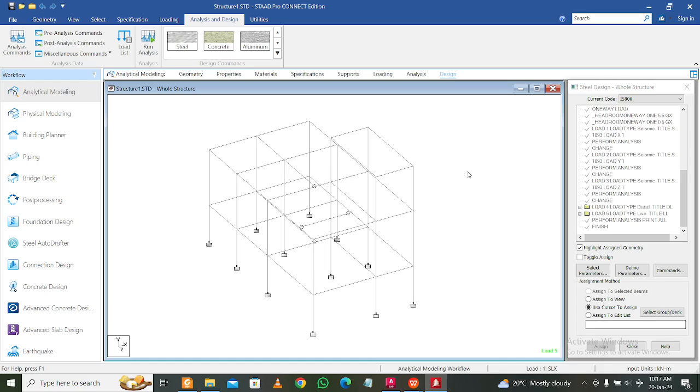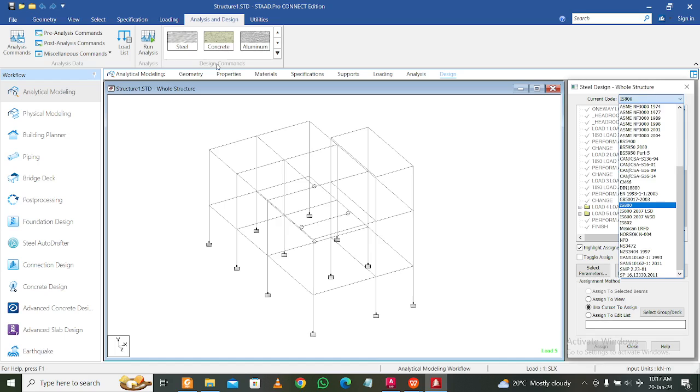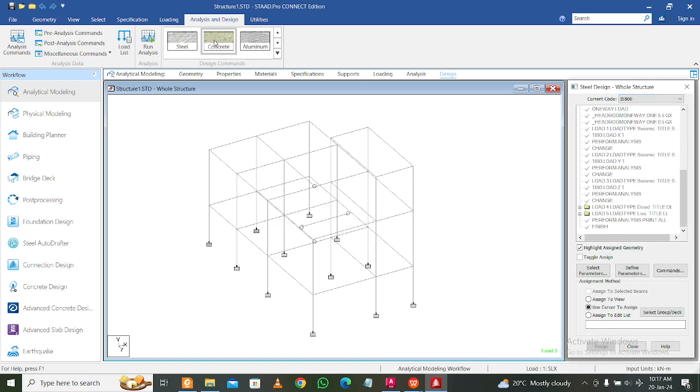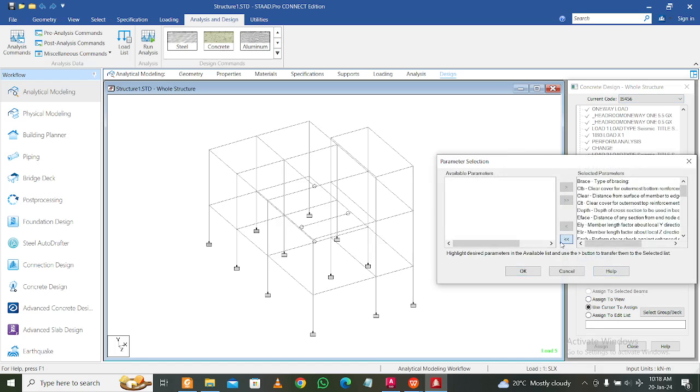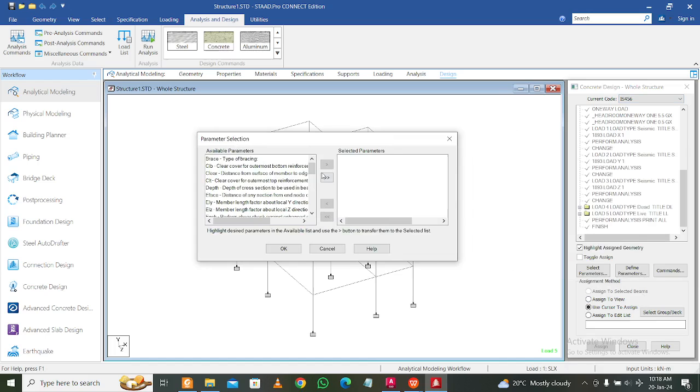Okay, so obviously concrete IS 456, just select concrete, then automatically IS 456 should come. If this is not coming, then go to the settings and change your default settings to your country code, then it will be coming here. Or if it is not coming for now, you can just select this from your drop down menu also. Don't stress too much.